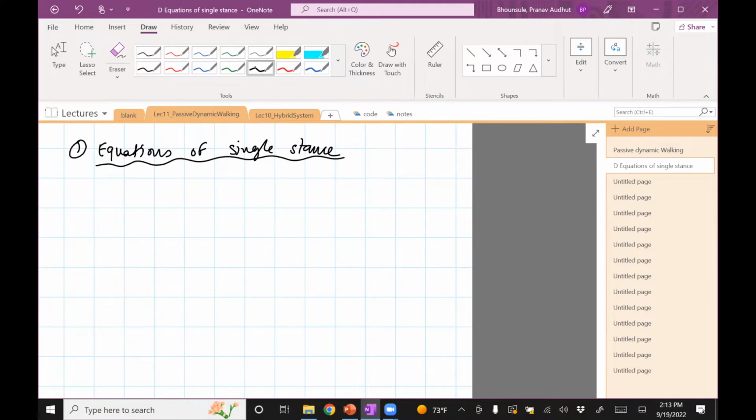Okay, now these equations are going to be very similar to that of a double pendulum, but there's going to be a difference in the sense that for a double pendulum, when we modeled it, we had 2 pin joints, one for the first link, another one between the 2 links, and it is to just move around that. Here, what we want to achieve is we want to continuously detach the leg from the ground and reattach it, right? So what we'll do is we'll use what is known as a floating base method to write the equations, and it will become clear in just a bit.